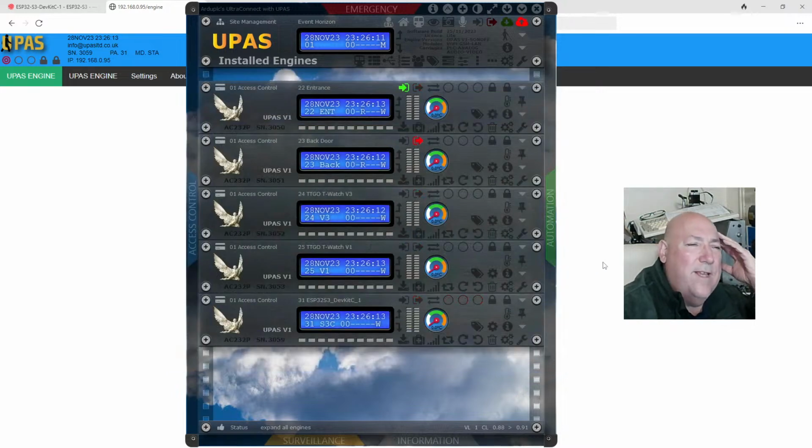It does a slave master thing. Now, it does a slave master, but if we're connected via unicast and each one's set up on its own thing, basically there's no need anymore to do it in order. That stemmed from when I did it on a RS485 half duplex, so you'd have to stop and wait and switch and request another one to answer. But I've kept it the same anyway.